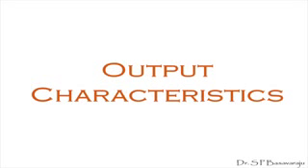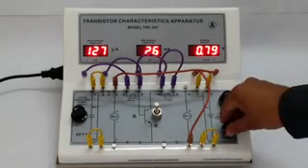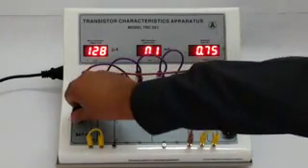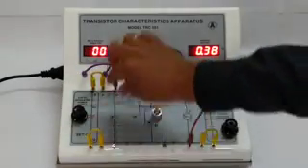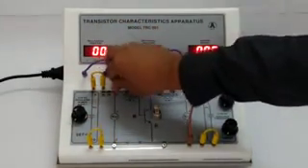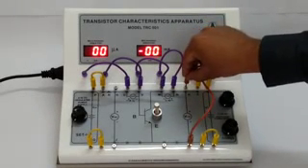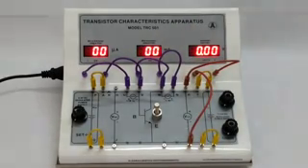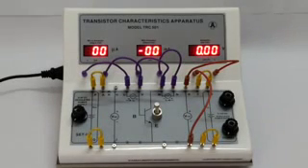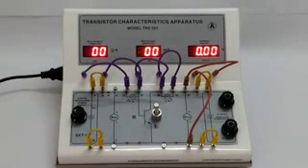Turn all the knobs to their minimum positions. There is only one connection to be made now, which is actually a reconnection of the voltmeter. The lead connected from voltmeter to the positive point on the circuit in the input side is disconnected, and the same lead is connected to the positive point on the output side. Now the voltmeter measures VCE.